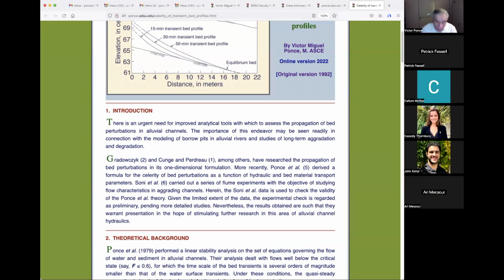So what happened, according to Wally, was that all that sediment that was in the bluffs came down and got into the river, but it was extra sediment. So the river doesn't have any power to hold the extra sediment. So in accordance with Lane's relation, it would drop that sediment at the bottom. The river is very large and it could do that.